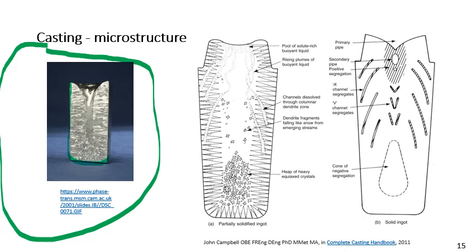Along the mold wall, there would be very fine grains. Then the columnar zone, where the grains are larger, visible to the naked eye here. And then closer to the center line, there are fine grains again that formed most likely heterogeneously out of the liquid. And a pipe is typical, this is called pipe, due to solidification shrinkage, and porosity can also exist in the last metal to solidify.